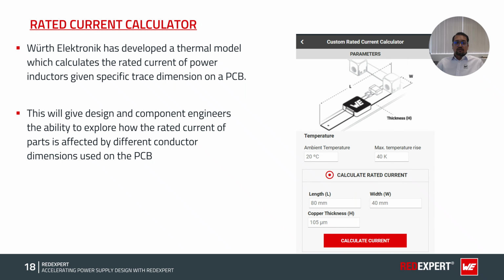Würth Elektronik has developed a thermal model that calculates the rated current of power inductors based on specific PCB trace dimensions. And this is important because thermal performance of an inductor is not just about the component itself, it's also about how heat is transferred to and from the PCB via the copper traces. This gives component and design engineers the ability to understand exactly how their layout decisions affect the current carrying capability of the inductor they have selected. It removes guesswork and helps you design with confidence.